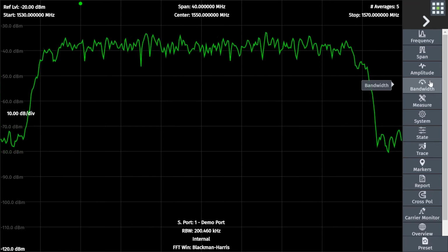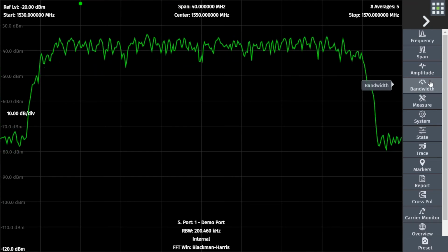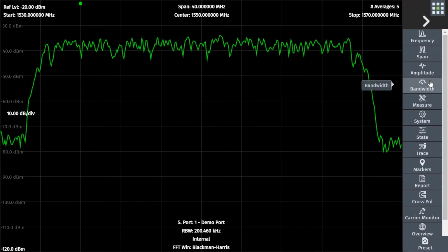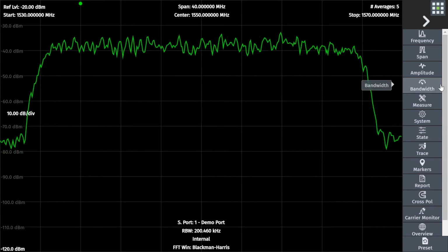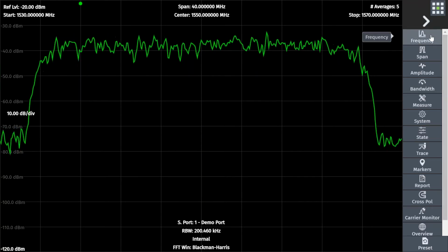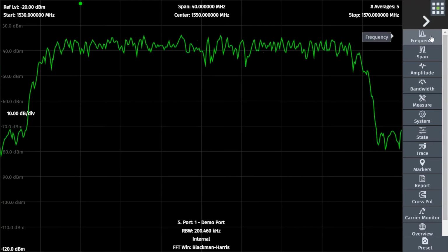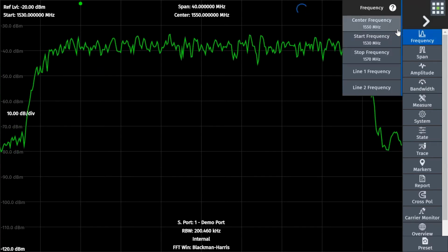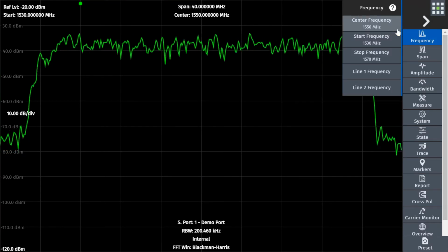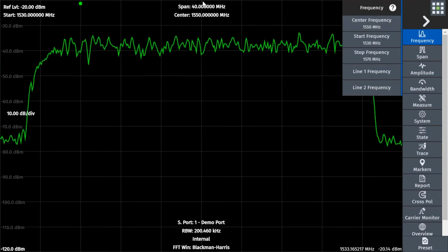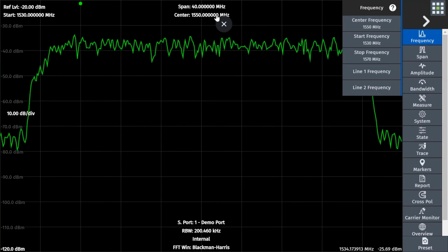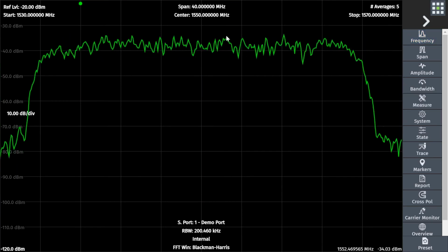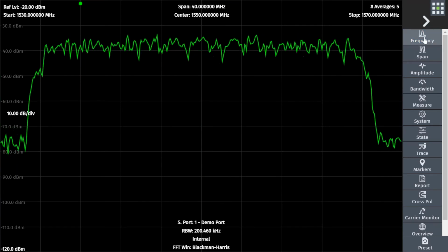Okay, so then past that, it looks like a spectrum analyzer, which is not surprising, and the core features are there in terms of capturing the spectrum. We'll just walk through some of the features and go through those in short order, just to see the various capabilities of the unit. On the frequency side of things, we've got the center frequency setting. Right now I'm set to 1550 megahertz. As I mentioned earlier, the full frequency range is from 5 megahertz up to 6.5 gigahertz.